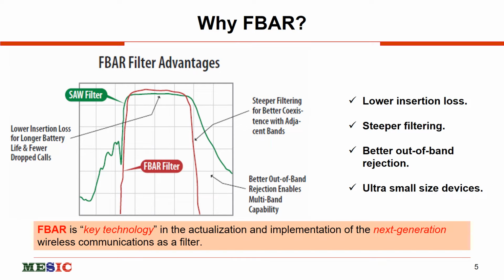So why do we need FBAR? As we know, FBAR is a key technology being used in 4G and 5G communication systems. It has low insertion losses, steeper filtering, better out of band rejection, and ultra small size devices, and low insertion losses will obviously affect the battery life of the device.